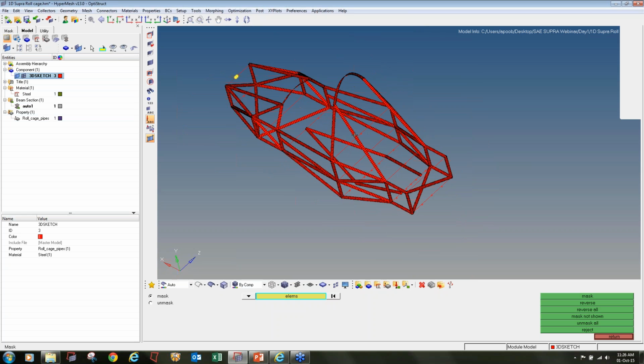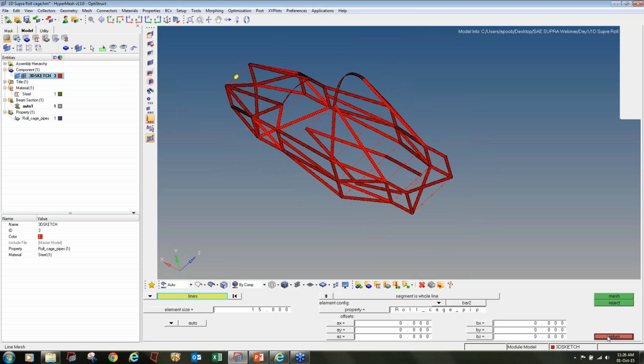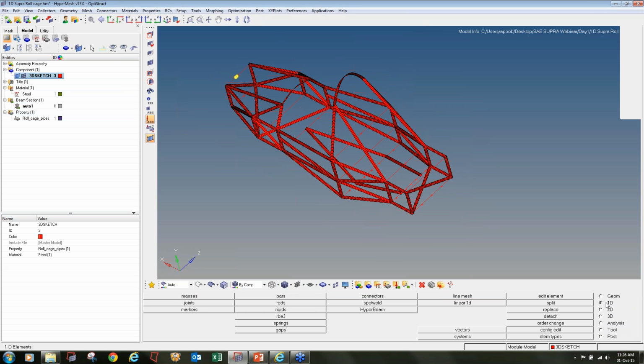So if my element length is in z-axis, then the cross section has to be in xy plane. If it's in zx plane or zy plane, then I cannot see a 3D element. So I have to update it manually. To update it, I will go to the 1D page. To update this meshing which is not proper, 1D page, bars panel,